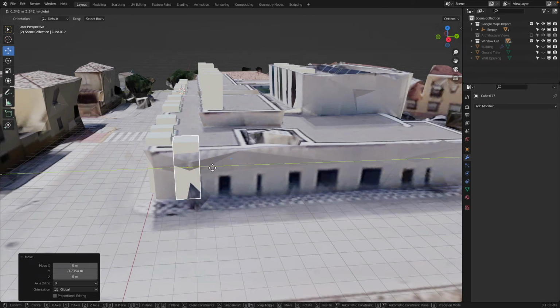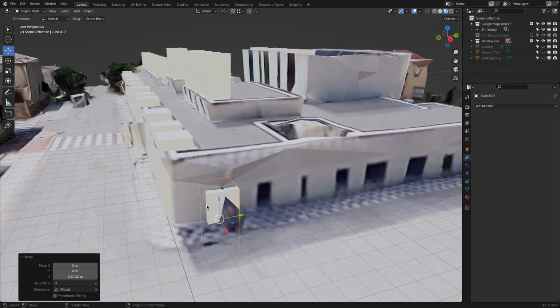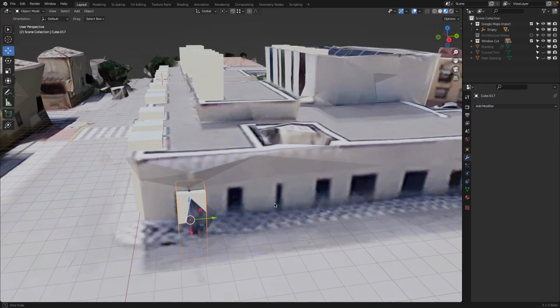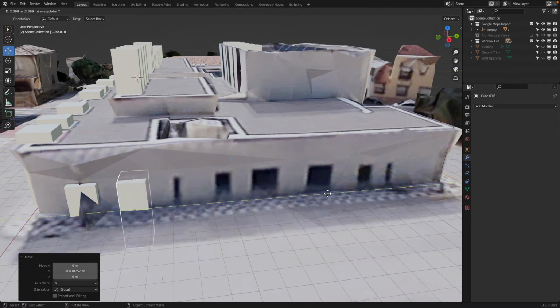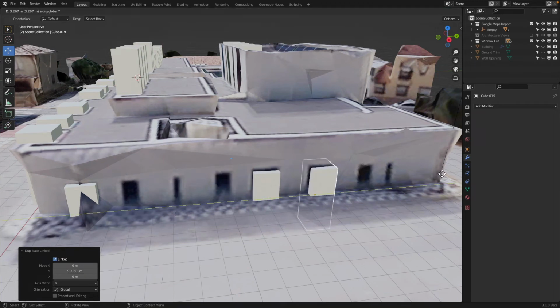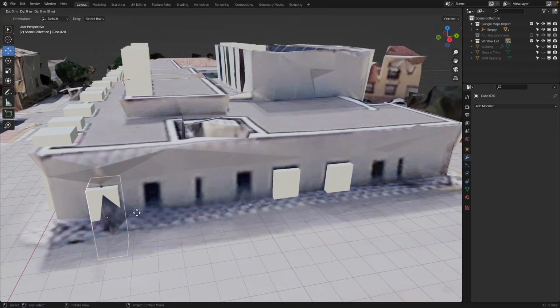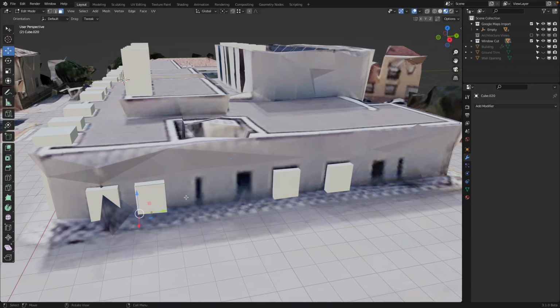Now I have to base everything more on the map there. Okay, so I bring this up, edit mode, face select this one, go to here. There we are. Okay, and then we have 2 there, so Alt D and Y, and I will do this kind of quick. Alt D and Y, block them out. There we are. So Shift D, G and Y, kind of like try to center it. Tab, S and Y, actually A, S and Y. I need to select everything.